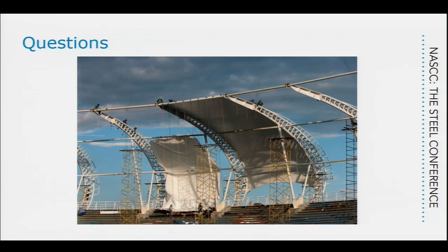Yeah. And off the top of your head, do you have any information on the factors of safety these manufacturers want? Typically what they do is they say a factor of safety of 2. So they give you, go to this stress, and you'll have a factor of safety of 2. It's what they will do, and then we do ours, precisely because these are not ASTM materials.